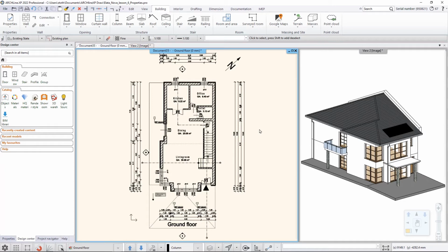And actually this is the purpose of this setting, that you won't be able to edit, remove, or make unnecessary changes on the content of layers that are locked. So this way you can actually protect parts of the drawing that you don't want to accidentally select, remove, or modify in any way.